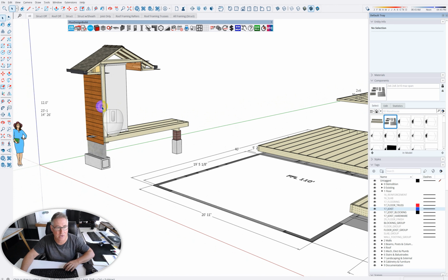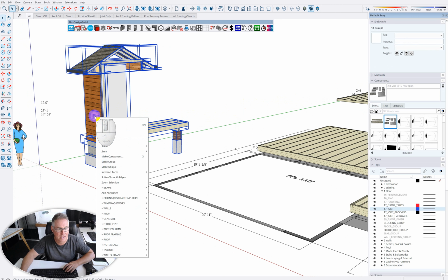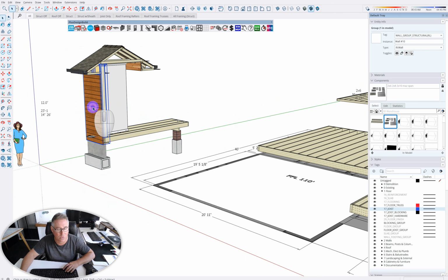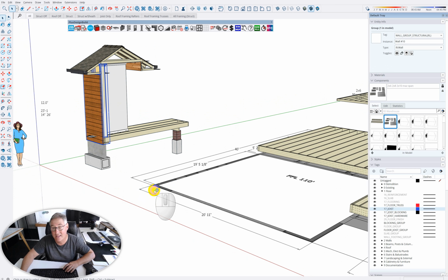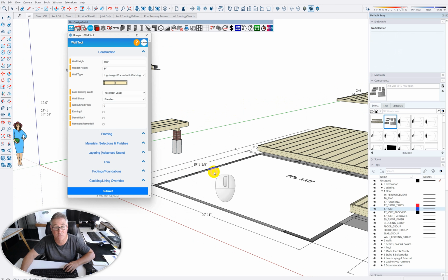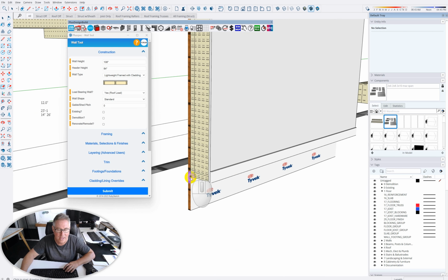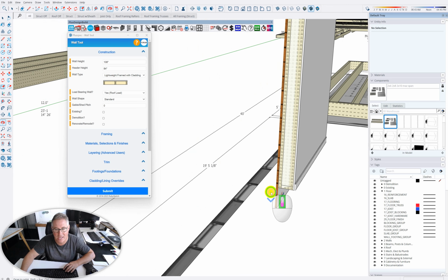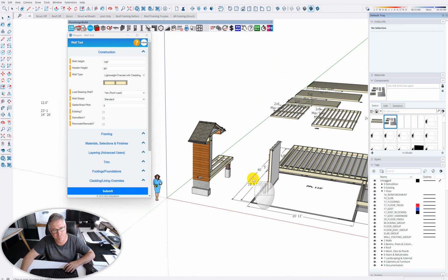And create similar is essentially when I'll explode this. We go right click and we create similar. So in a wall, right click, walls, create similar. We can do the same with joists, and that's how I'm going to show you guys how to put spans into joists. So if I want to draw a wall here, I'll just put it here. That just basically copied the wall. And the reason why this is important according to joist size is the step down for our cladding will go down lower according to the joist size.